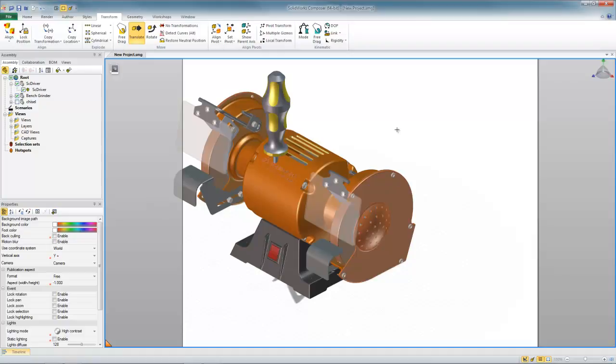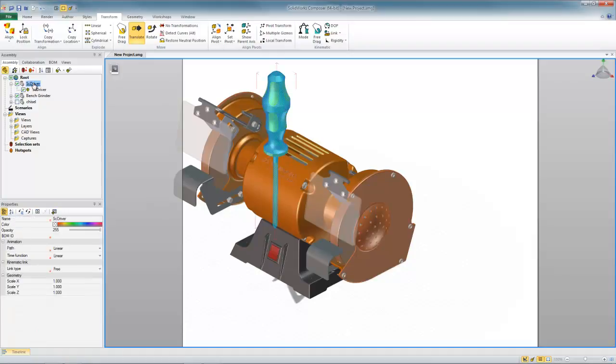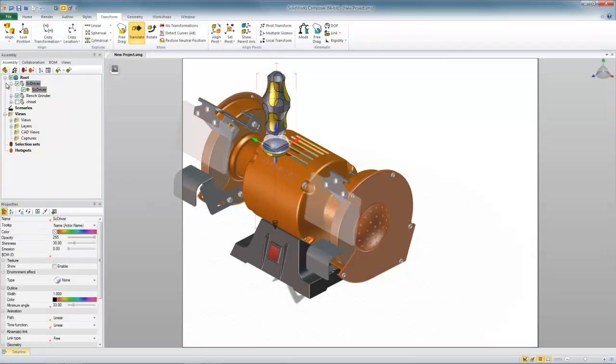So to do this, first of all, you'll want to select as a part, not an assembly. And the way you tell the difference there is when I select on this screwdriver, if it highlights all in blue, that's an assembly select. We want to actually select all of the parts as a group. So just uncheck or depress the assembly selection mode so that turns off. Now when I highlight that, you'll just see all the parts selected. On your screen, it may show up as an orange color, depends on your settings.